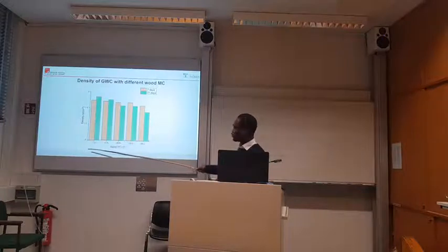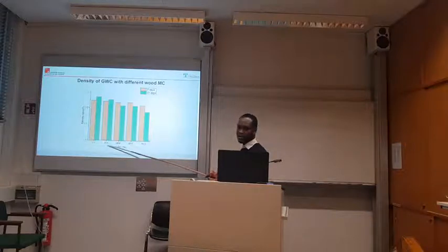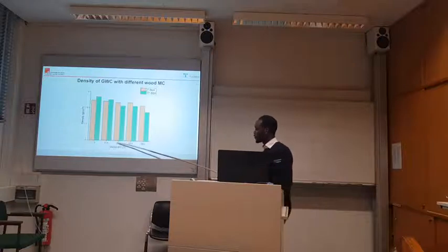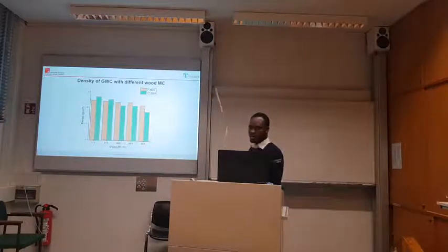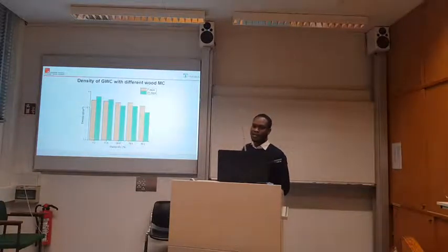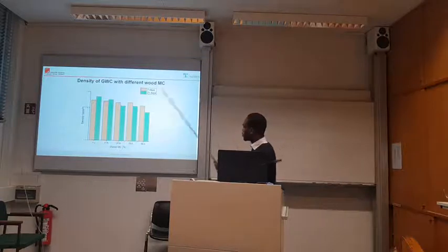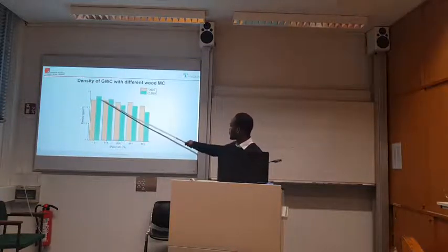and we start with wood that is totally dry, so wood with moisture around 1.3%. And we have wood that is around the equilibrium moisture content, around 12%. Then we have wood that is around fiber saturation point, and wood that is above, 60%, and wood that is almost 90% water. So every component is the same, but the wood that is added has different moisture content. What is happening here is for 7 days and 21 days.